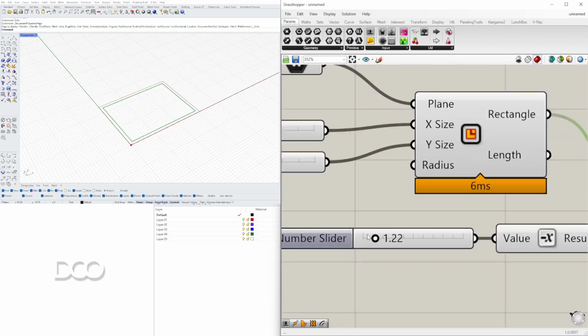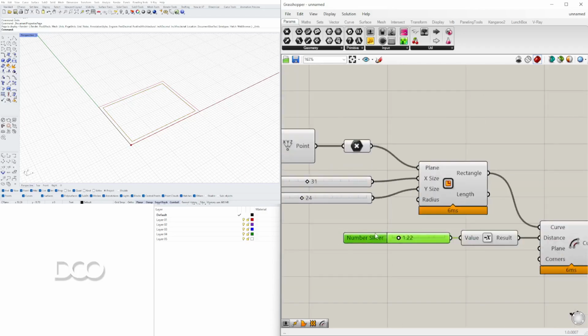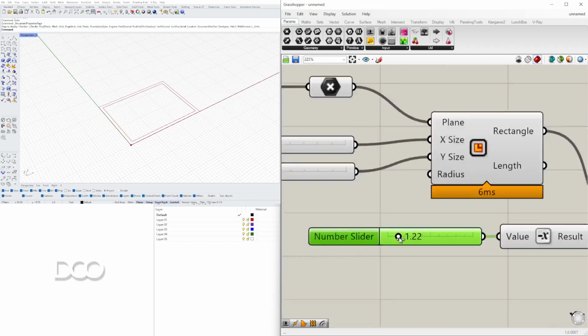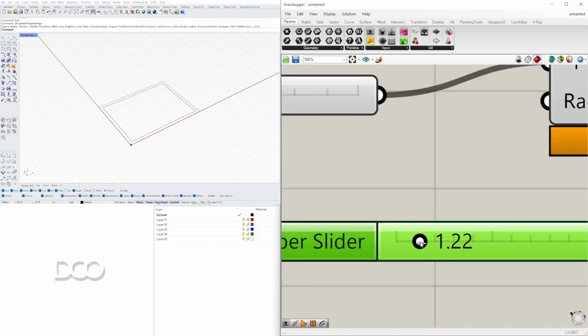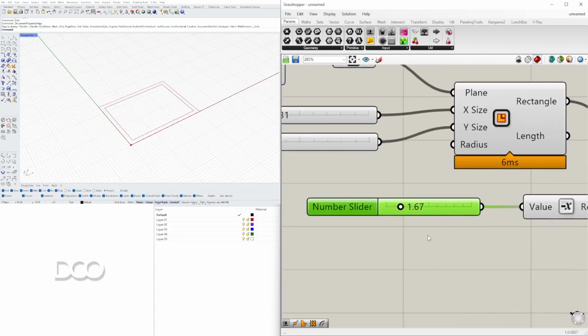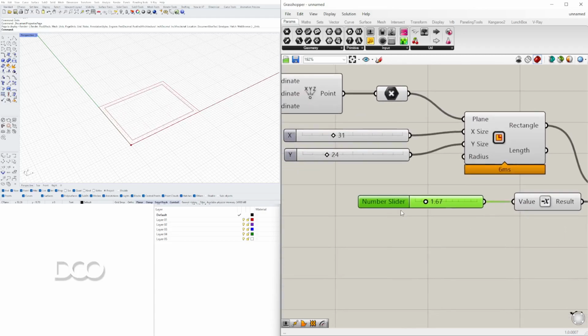Now what happens is technically walls are dimensioned in lumber, which is dimensioned in inches, not in feet. So for this to be, let's say, an 8-inch wall, I can't just go to 8 because that would be 8 feet. And I can't go 0.8 because that's going to be too small. So what we need to do is convert it from feet to inches.